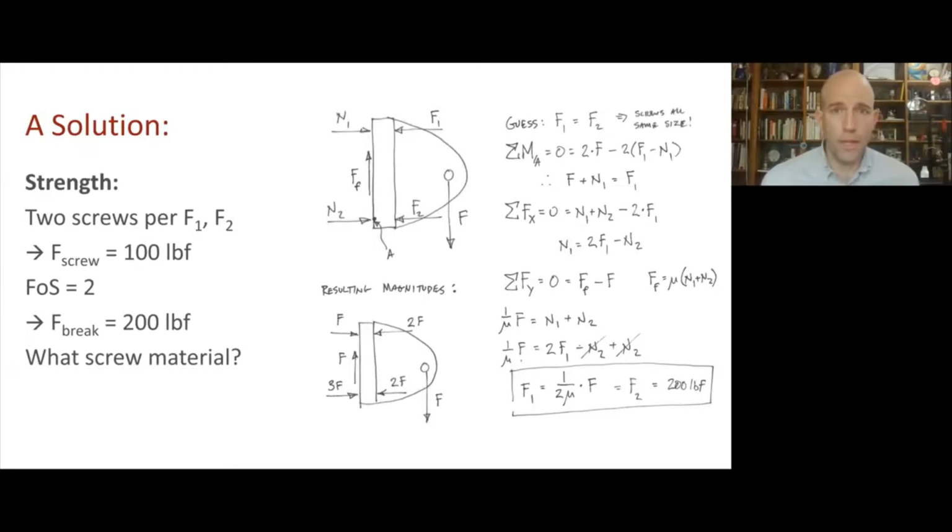All right, did you come up with a guess? In this case, very frequently it's nice to have a really strong material, and especially a material with a good strength to density ratio. That's a commonly useful material factor for these kinds of mechanical elements. And hardened steel is really good for this. And that will result in a small component, so it will add less space to our system. And if these are chosen optimally, it'll result in a component with low mass. And hardened steel screws are ubiquitous because of these reasons, and that also results in lower cost. So hardened steel is probably a good choice here.